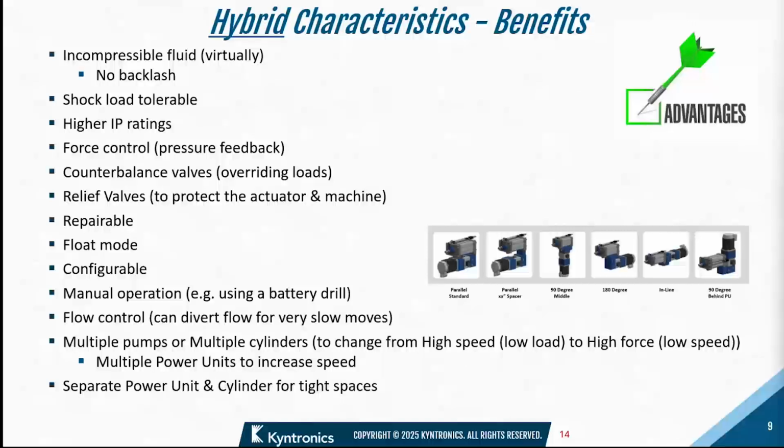So we can do that by diverting flow and doing some flow control there. Also, with fluids, you can do multiple cylinders to increase speed, multiple pumps, or even power units. So you have some flexibility with hydraulics to add flow and increase your speeds as needed. The last on that list is you can have a separate power unit and cylinder.